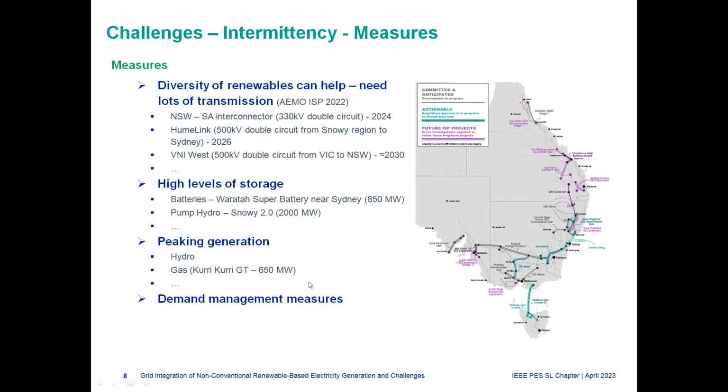In addition, we are looking at demand management measures as well, because there can be loads that can drop if we are short of supply, especially aluminium smelters or large loads. We are looking at having contracts with some large generators, large loads, large customers, so that they can reduce their generation, or they can go to internal gas turbines or diesel generators, and reduce the grid demand.